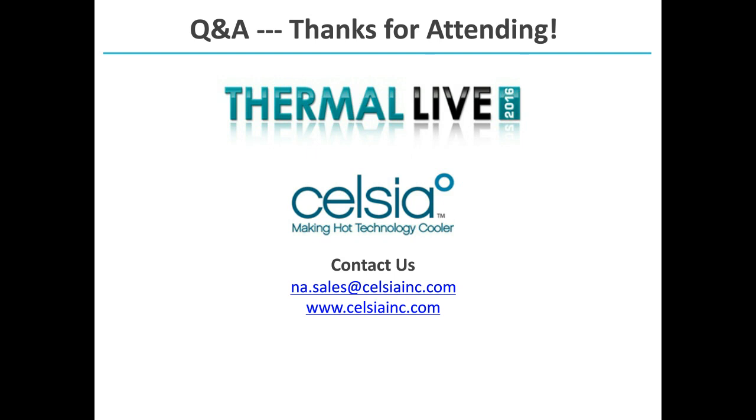I'll just walk you through one. You put the liquid in, and it's just like a refrigeration system. You put the liquid into the device, and you draw a vacuum on it. What that vacuum does is it draws the air out. It also then draws out a little bit of the water vapor, and then you seal it off. So what you have is only the working fluid in there under a vacuum.